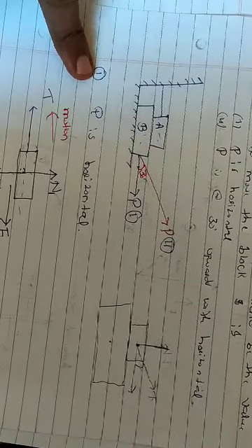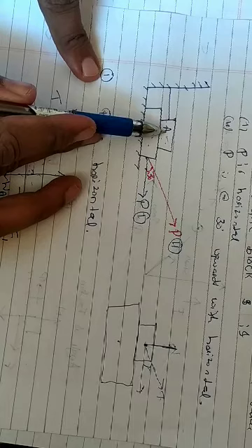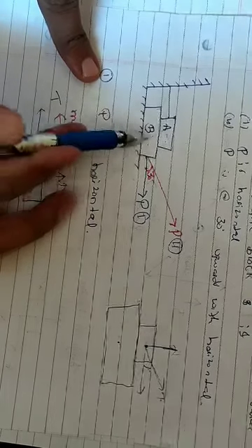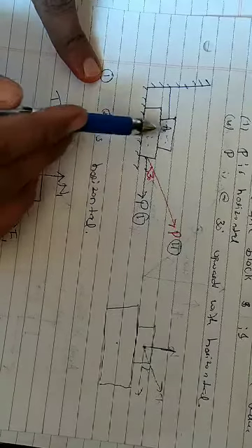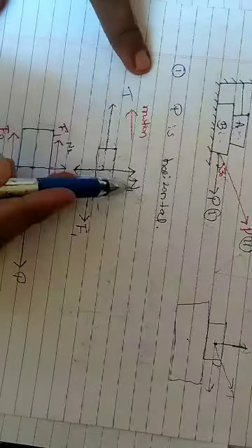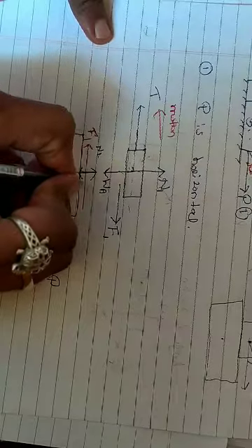So in general what we can say here is that the summation of vertical forces which is acting on body A will be transferred to body B. Simple, right? Summation of vertical forces acting on body A is nothing but the normal reaction, that is N1. So N1 will transfer to body B. So this is N1 also here, you can indicate N1, okay.